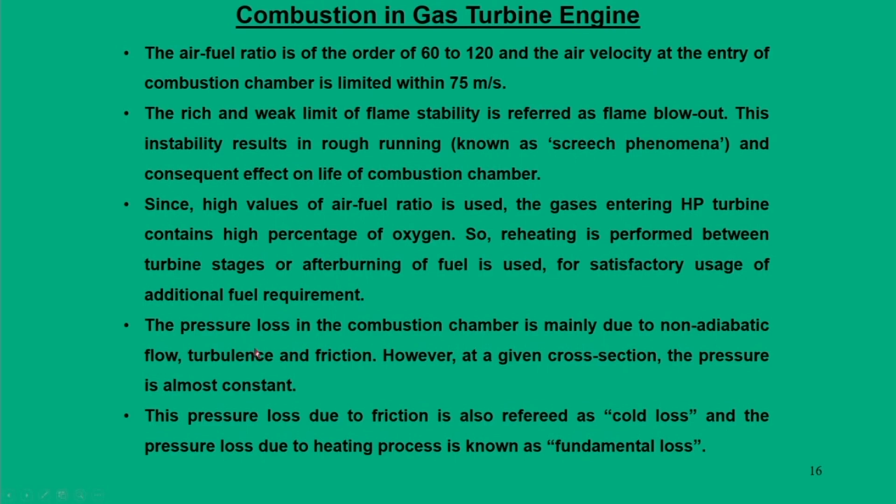Of course, there are some pressure losses we have been mentioning in our analysis, and this pressure loss is mainly due to non-adiabatic flow, turbulence and friction. There is a continuous pressure loss, but at a given cross section the pressure may be treated as almost constant.